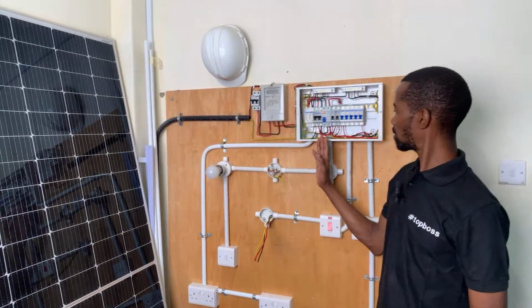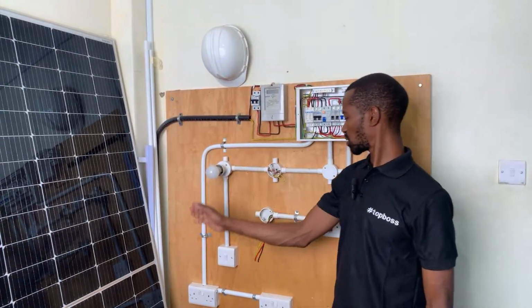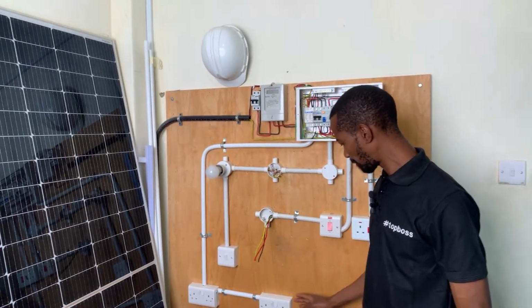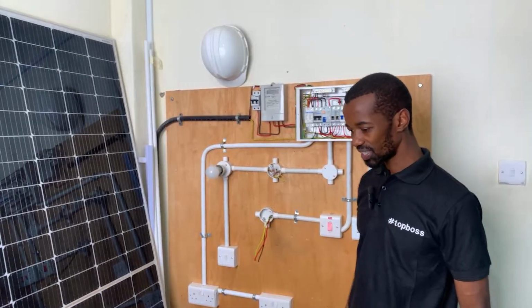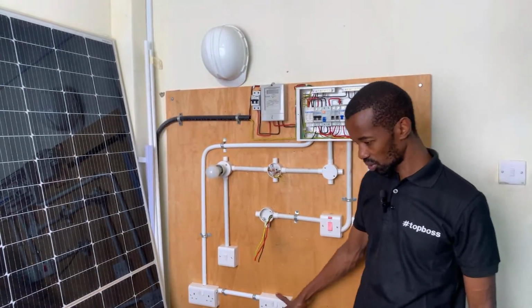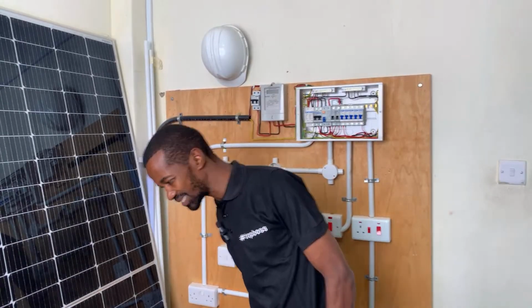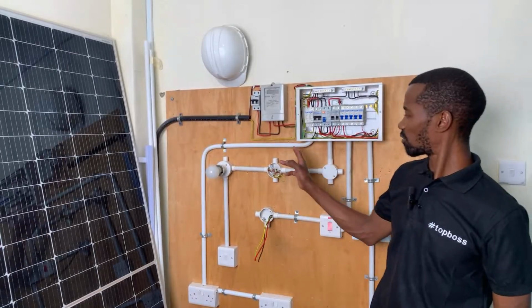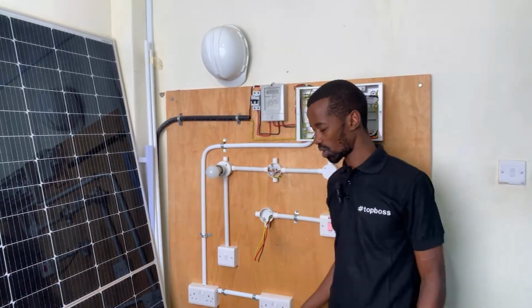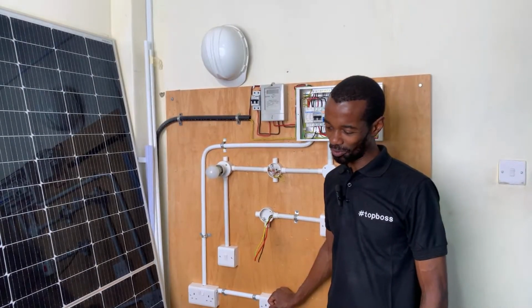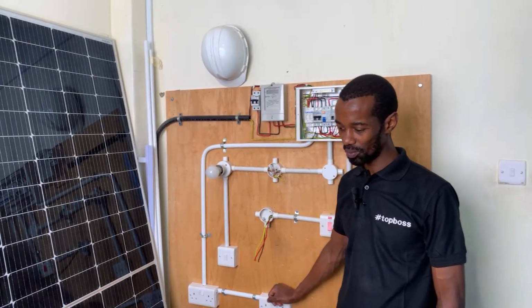So from the consumer unit, it goes to the first socket, the second, we could even have another one here, and then that's it. We know that there is another one that goes back to the consumer unit. So which one is this one? And Joe is very right, it says radial. Why? Because radial starts from the consumer unit and goes to a point where we can say a dead end. It does not form a ring, it does not go back to the consumer unit.